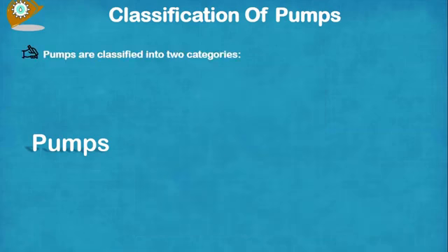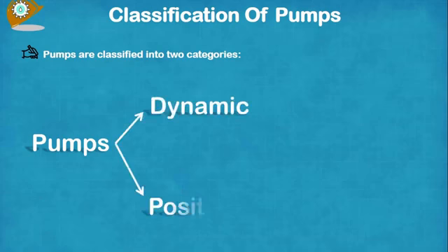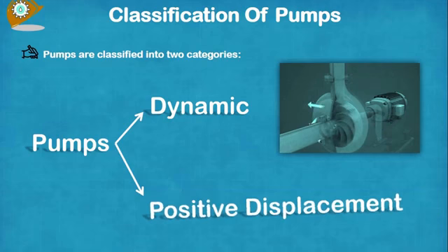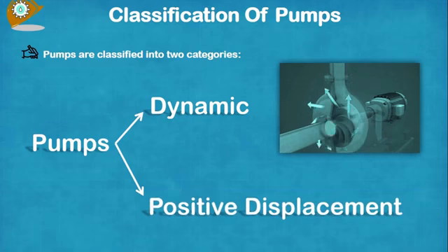Pumps are divided into two fundamental types based on the manner in which they transmit energy to the pumped media: dynamic or positive displacement. In dynamic displacement, a centrifugal force of the rotating element, called an impeller, imparts velocity energy to the fluid, moving the fluid from pump suction to the discharge. On the other hand, positive displacement uses the reciprocating action of one or several pistons, or a squeezing action of meshing gears, lobes, or other moving bodies, to displace the fluid from one area into another.